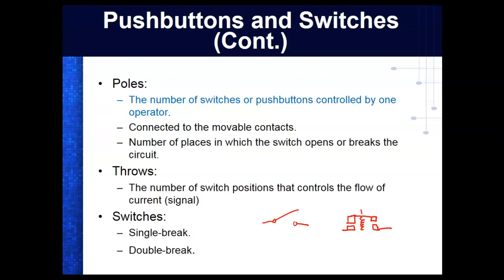I need to draw this because it's recording. If one side's welded together and it breaks, it literally tilts up and has a tendency to break the weld. So these guys have two chances to break a circuit. Single break contact only has one chance to break the circuit. A double break contact has two chances to break the circuit. And plus, on a double break, you can actually see on that one, if you touch it, you can actually move your finger.